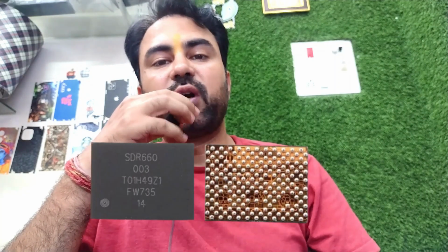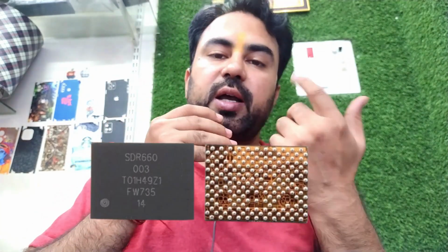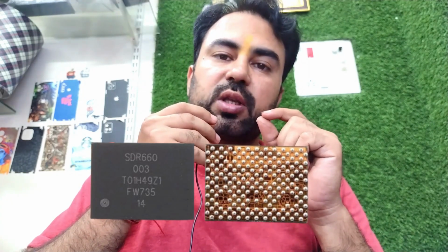Now in this video we discuss the SDR IC. What is the difference between the WTR and SDR IC? The SDR IC is used in the latest phones, in place of the WTR IC. The most common problem in latest phones with an SDR IC installed is a baseband problem: SIM not detected, unknown baseband, or other network issues, but with the WTR IC you will see no service issues.